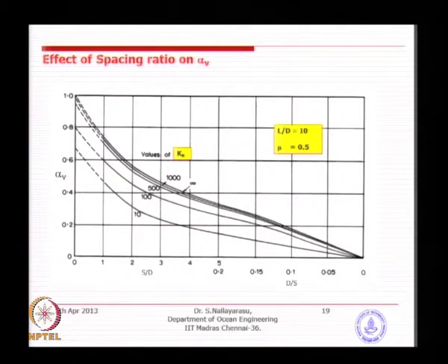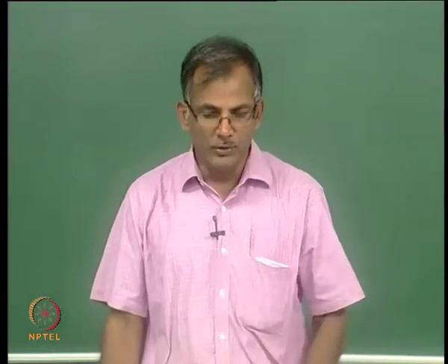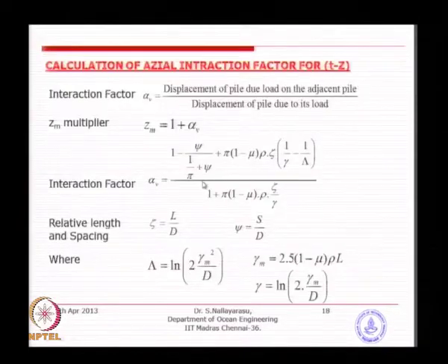So, you can straight away use it whenever you have only a 2 pile system, because you can't use this procedure for anything else. It is specifically for a 2 pile system, and if you have more than 2 piles you have to come up with some additional methodology to take the effect into account.